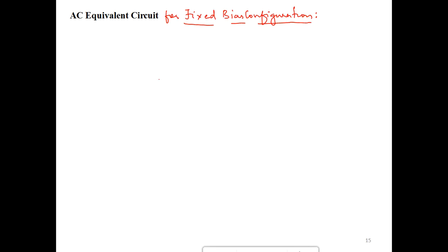So how do we do that? That's the gate terminal, and the source is common and it is being held at the ground potential. Let us give it a minus symbol, and plus minus, the input impedance is infinite, so it is just open circuit, and VGS is the input voltage which actually controls the entire device.